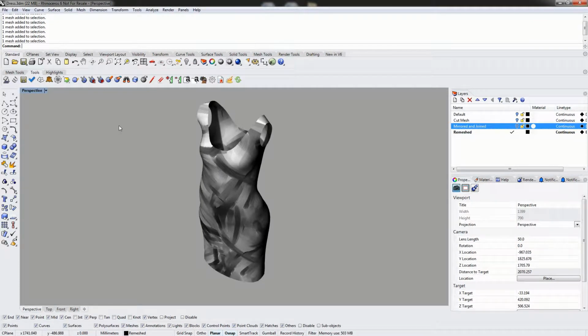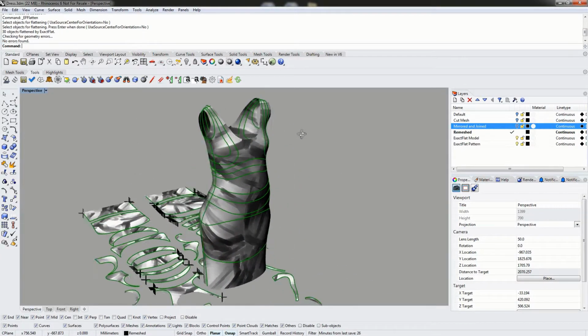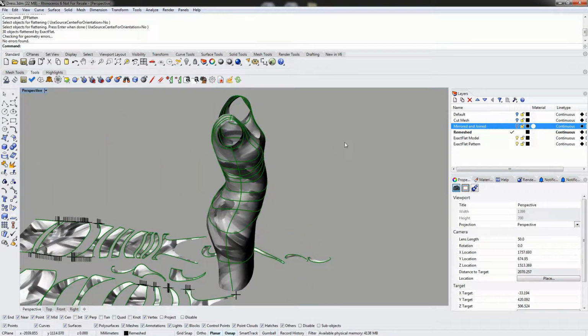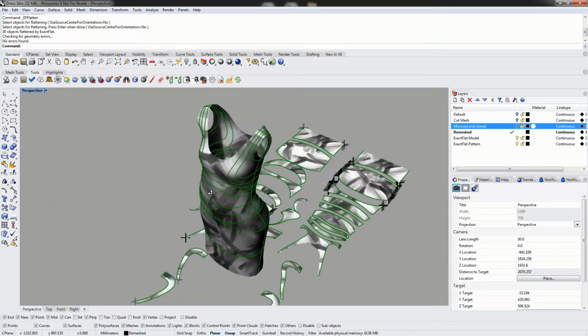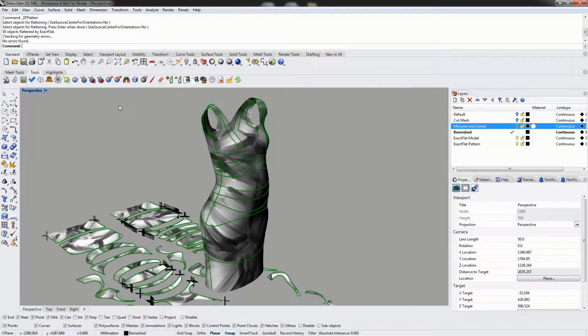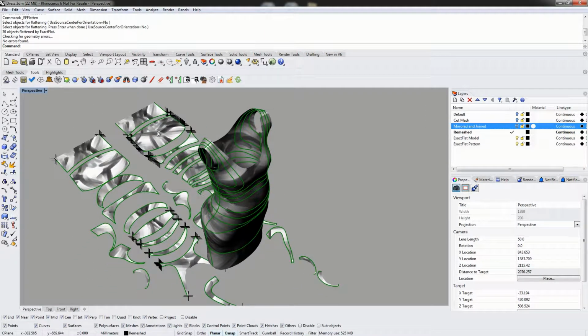To begin, we will use the ExactFlat flattener, the very first icon in the ExactFlat Tools toolbar, and we're just going to simply rectangle select all the meshes here. Now this particular model does have a lot of pieces on it, so instead of flattening all these pieces separately, we're going to use the ExactFlat cutting tools to remove some of these cuts. Before we do any kind of pattern processing, before we even use the pre-flatteners to remove our strain and sag, we're going to use the ExactFlat delete cut tool, and we're going to remove some of these cut lines.